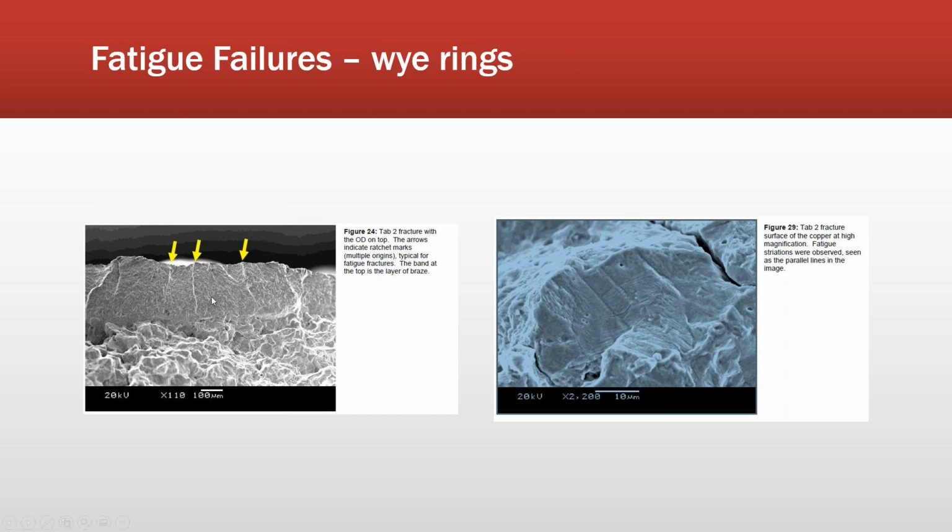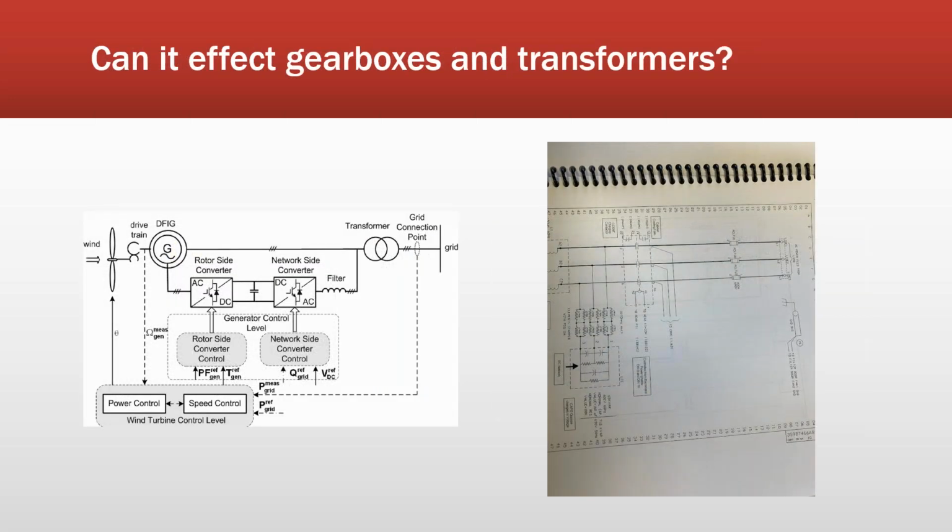But it turns out that all those Y-ring failures are fatigue related. So flexing. So as I have starts and stops, it's not stationary, it's moving. Part of the reason why the Hitachis seem to go first, they have a slightly thinner Y-ring than some of the other ones. And some of the ones that have the thicker Y-rings last longer. But I guarantee you, for a fact, every manufacturer has that problem. Several of them are now using our technology to do studies on that very thing.